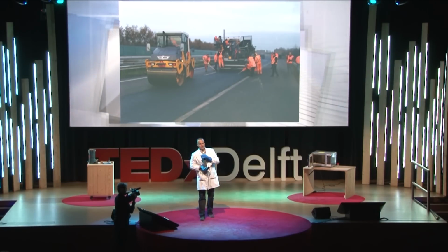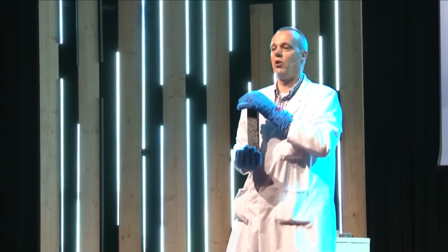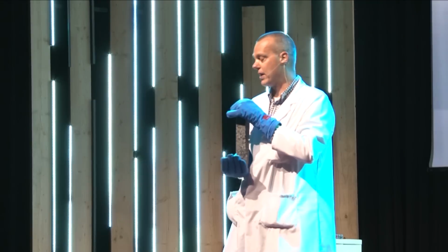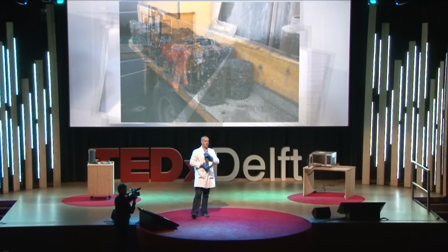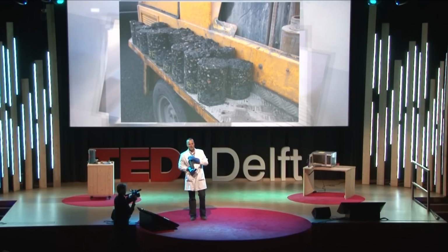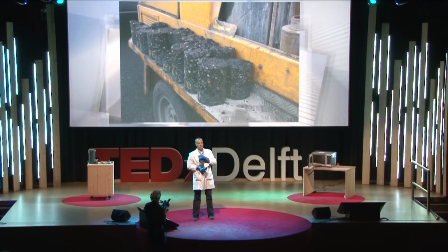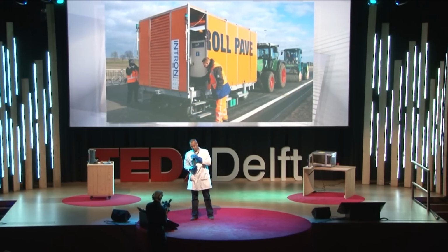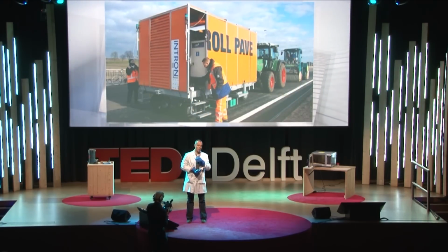And then, of course, this road will last several years without any damage. That's what we know from practice. So we took a lot of samples from this road, and we tested them in the lab. So we did aging on the samples, did a lot of loading on it, healed them with our induction machine, and tested them again. Again, broke them, healed them. Several times we can repeat that.